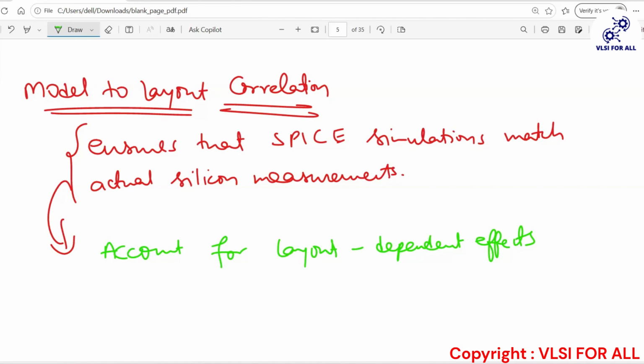All these stress conditions you need to evaluate beforehand, so the device model should have all those things to account for them, so that you can predetermine them. Because if you lack something, this will result in yield loss, and yield loss means your chip will not be passed to go to market. It will be discardable.